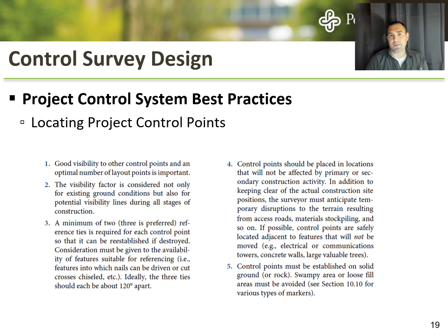Just to think of some common sense best practices, if you were responsible for locating, measuring and laying out during different phases of a project, what strategy would you use? You'd disperse your points, make sure you had a good line of sight, put temporary monuments where they're not going to move, and have redundancies. Those are the big picture things that I want you to think about as you're brainstorming what you would do. We're not going to go through a whole exercise to do that. Even when we do have in-person labs, it's not something that we do, but it is something that you should be thinking about.